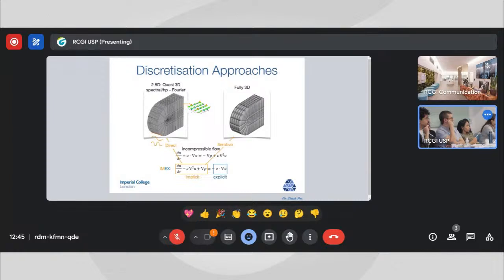So there's an assumption that it's periodic in that direction. As long as you keep that periodicity, that should work fine. But if we're trying to solve the same problem in 3D, and for the car type problem, we have solved it in 3D. Yeah, just to compare with the solution, you might have higher frequencies in that direction. Yes, so at one frequency, you can multiply by a Fourier mode, and it will put energy into a higher frequency. And so it depends on how many Fourier modes you have.